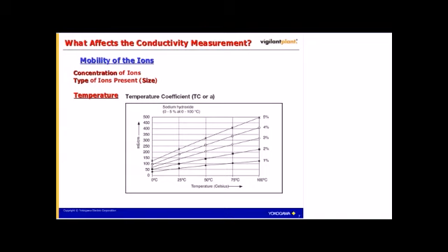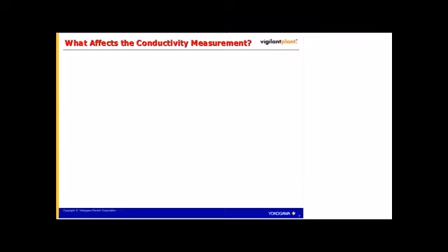In some pharmaceutical applications, it is desired to measure uncompensated conductivity value as alarm set point for impurity levels. But this value is not really practical for process control. We need to have temperature control in order to have an effective measurement.